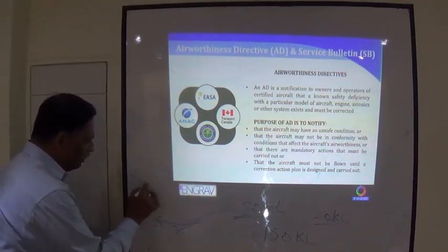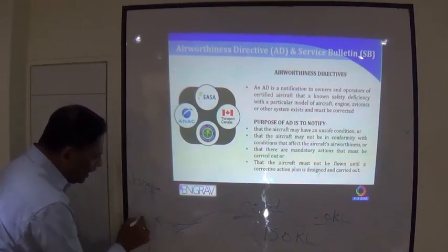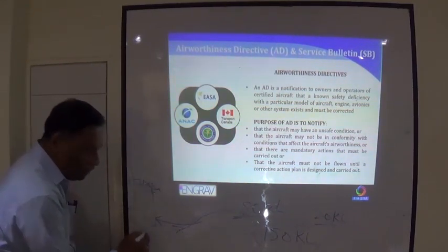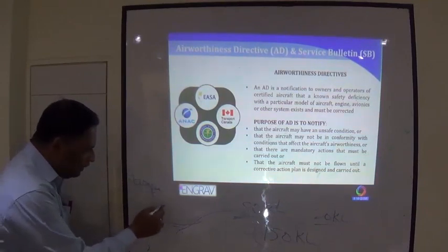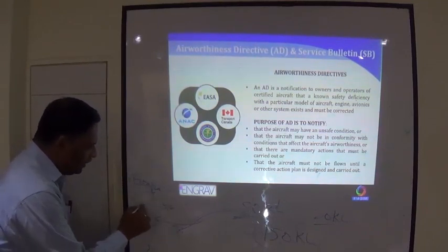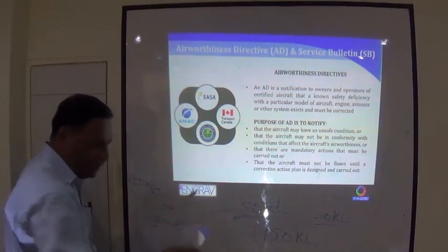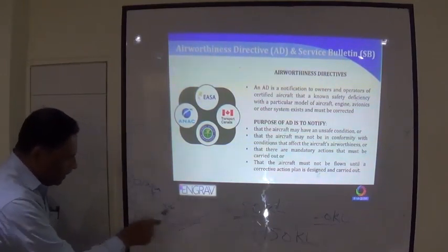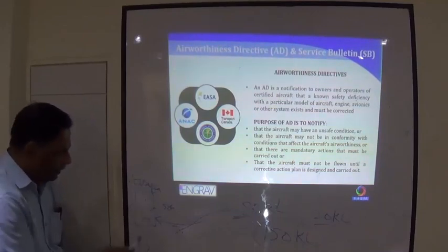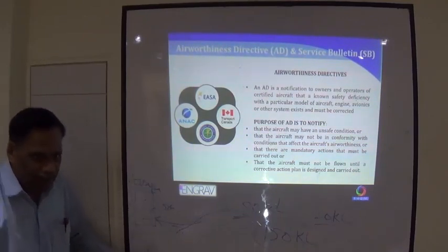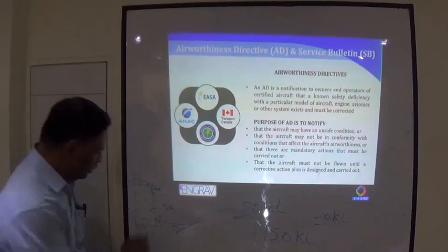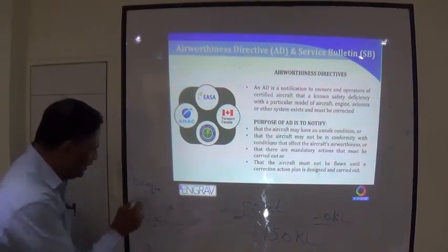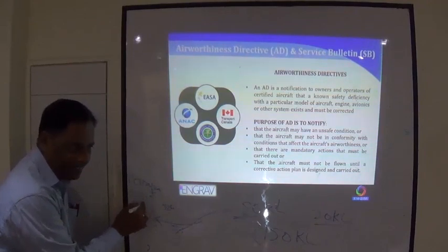Here you maintain a negative pressure, vacuum. Under the negative pressure, even at a 50-degree temperature, the water starts boiling. So you take seawater, circulate it over the engines and the generators, bring it into the evaporator system, where vacuum is maintained, then it starts boiling. So you boil it, and the steam goes and deposits, distillation.